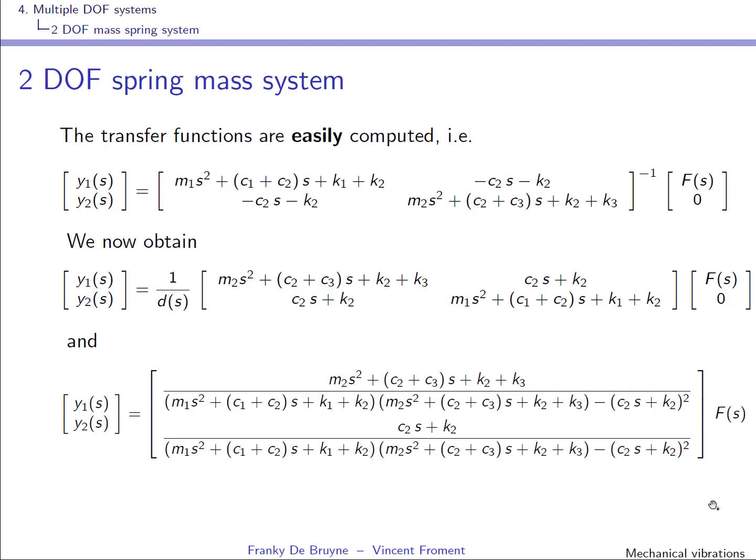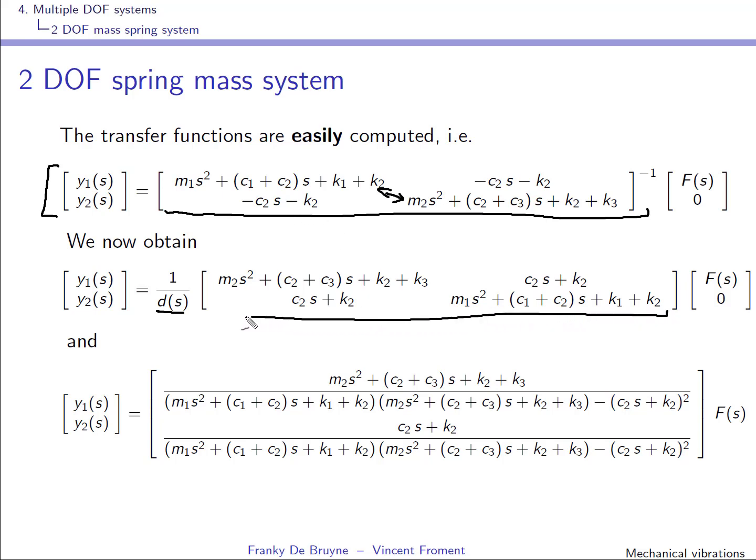Well, we had arrived at this expression here, and you can now write the transfer matrix by computing this matrix inverse. Okay, that's easy, as said over there, because you can invert a 2 by 2 matrix. Well, it's 1 over the determinant, right? These ones change place, and these ones simply change sign, okay, and you obtain this matrix over here.